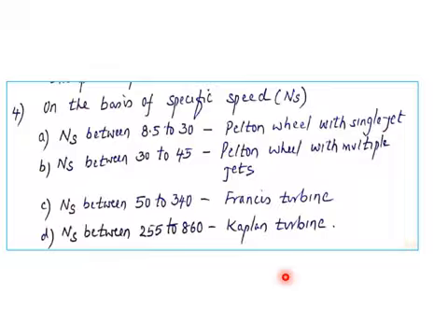You saw that the Pelton wheel was an impulse turbine, and also a tangential flow turbine because the water hits tangent to the pitch circle like this. Then we had the Francis turbine, which was a radial flow turbine and works under medium head. And the Kaplan turbine is an axial flow turbine where water moves axially, parallel to the axis of rotation, and it works under a low head. So different turbines have different specific speeds.